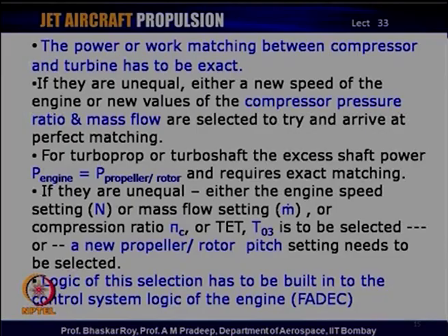Now, this power that is required by the propeller and rotor is to be decided by the propeller rotor designer and is to be supplied to the engine designer, or the propeller rotor designer has to design exactly for the amount of power that is available to him for a selected engine. So, this again requires exact matching at every instant of operation of the engine.